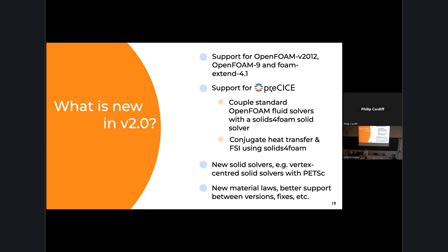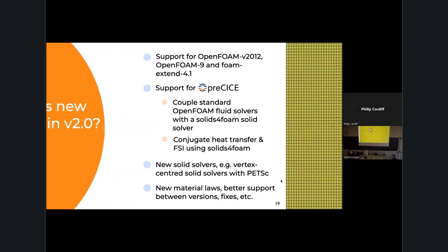Now I worked with the developers there to make an adapter, as they call it, for solids4foam. So now you could use the solids4foam solid solver with a standard OpenFOAM fluid solver if you wanted, or you could use it to couple a solids4foam solid solver with a solids4foam fluid solver. There's no reason to do that, but you could, or solids4foam with another fluid solver. And there are also some new solid solvers, vertex-centered finite volume ones that are based on the PETSc linear library, new material laws, bug fixes, etc.